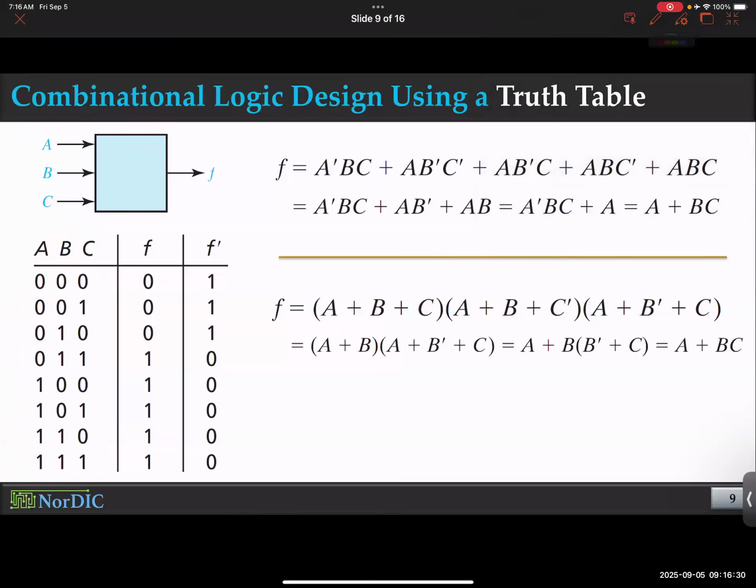And we found a way to express any Boolean function that is represented by 3 input combinations in a format that is compatible with Boolean algebra, for example. So something that we could handle with Boolean algebra later on. This is a very powerful approach because it's universal in a way that you don't have to manually think about implementing this function every time. You could just follow a rule and it will work every time. That is a big deal.